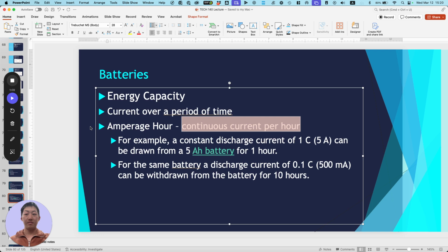Now, this thing doesn't show it, and I could bring it next time. I have this charger, the HOTA. It will give you a lot more level of detail. It'll also tell you impedance on the cells. Impedance is basically like resistance, which is not good. Lower number is better. So maybe as a baseline, while we have new batteries, we should plug it in and see the impedance, because that's only going to go up over time. So we can use that as a baseline.